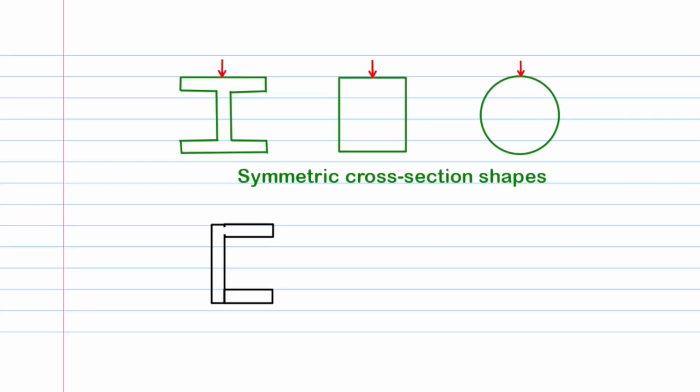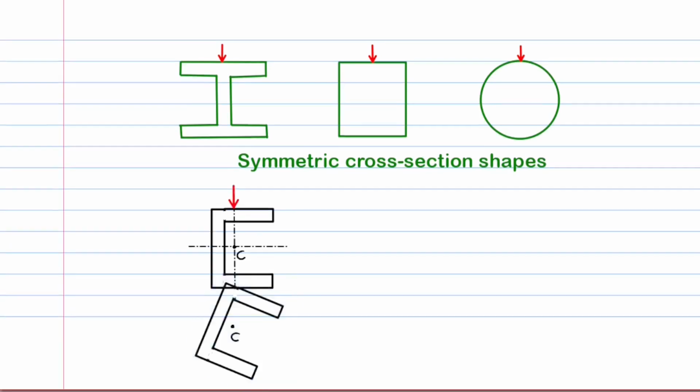If this were not the case and the section was unsymmetric about the vertical plane passing through the centroid, then the horizontal beam would not simply bend but would be associated with twisting about the horizontal z or polar axis due to the shifting of an imaginary point called the shear center from the centroid to some location offset along the x-axis or horizontal axis.